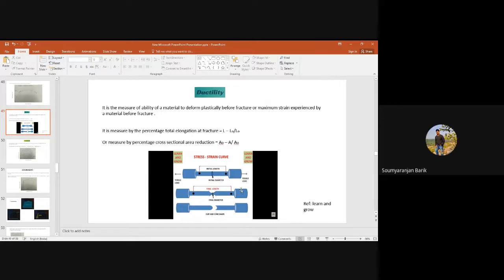So that does not undergo any deformation. Actually, as I told in the initial part, the gauge length portion has a fixed or constant cross-sectional area before the test. If you measure the cross-sectional area at any point, it is the same. But far away from the gauge length, the cross-sectional area may change. It may increase, right? And in the grip portion, it is maximum. Okay, anyways,